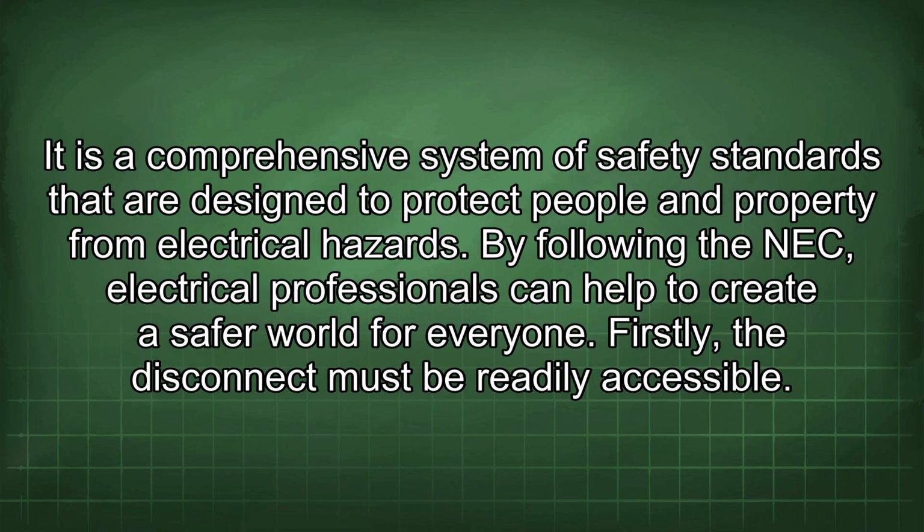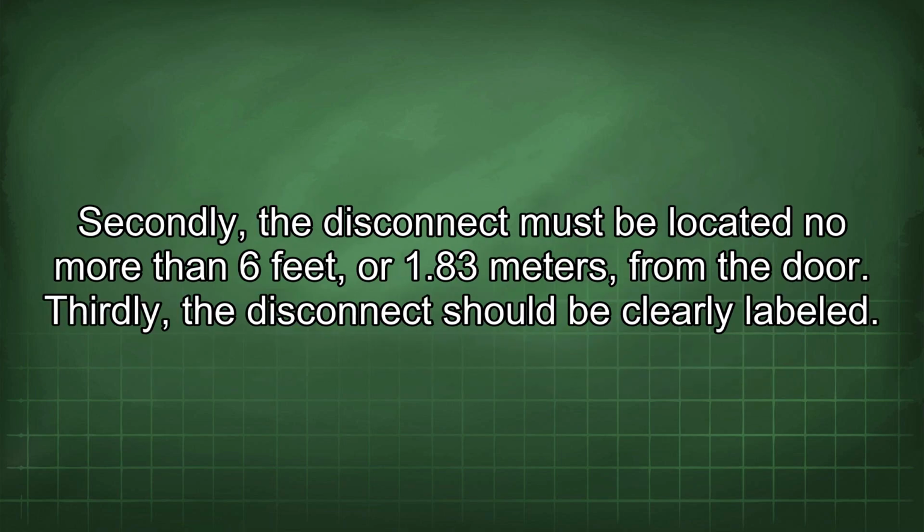Firstly, the disconnect must be readily accessible. Secondly, the disconnect must be located no more than 6 feet, or 1.83 meters, from the door. Thirdly, the disconnect should be clearly labeled.